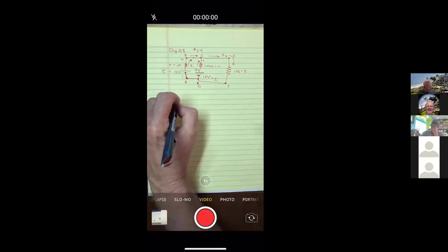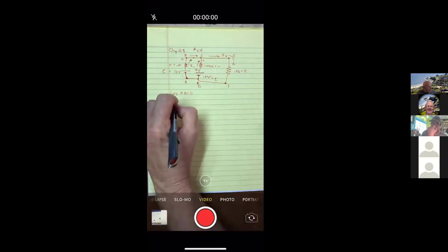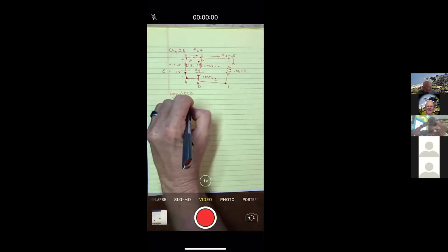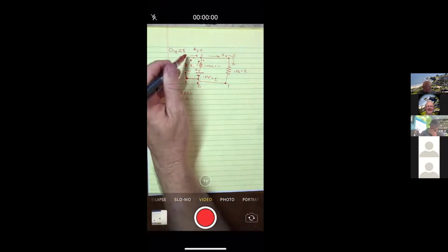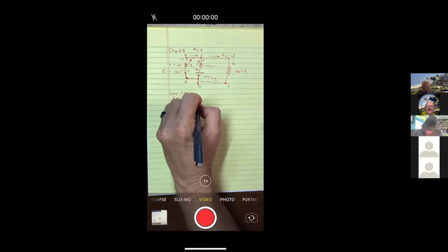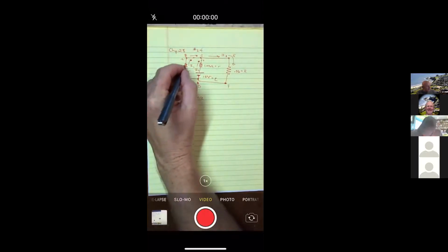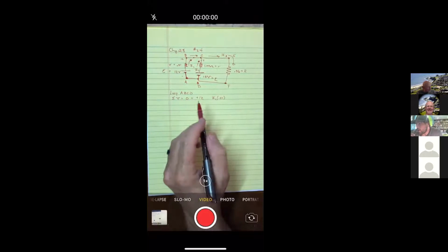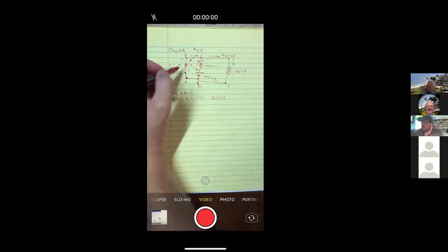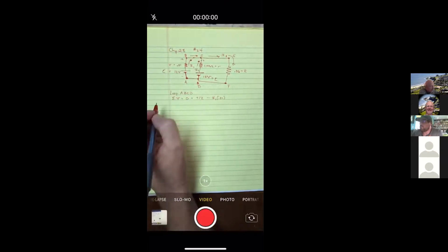Yeah, so I think you hit it there, that if I do the loop A, B, C, D, and I add up all the voltages around a complete loop, I'm going to get 0. So from A to B, I would go an increase of 12, little bar to big bar. Then I would have what I've called current I1 and a resistance of 0.01. That's Ohm's law. And I've got to pause and say is it a positive or a negative, and I'm going with the current, so that's a negative.